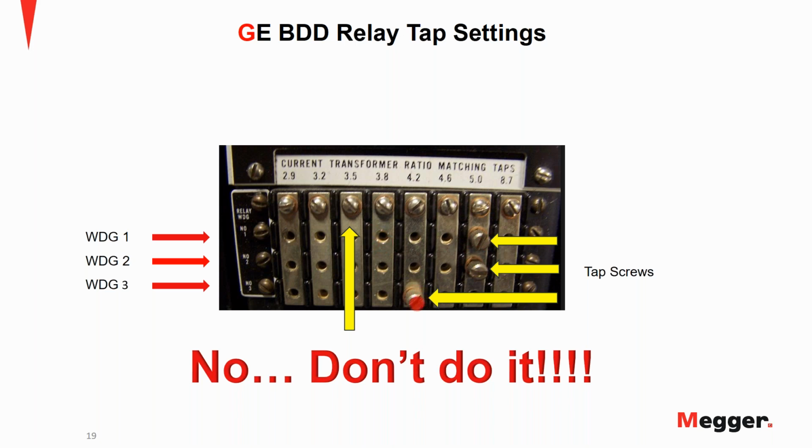If you decide that one day you want to tighten these up a little bit with the inspection you do on your electromechanical relays, and you twist this guy just a little too much, then he's going to end up breaking this head off. That's a bad day, I'm not going to lie to you. This is when you pull this tap out and you put it in this relay and you twist the head off of it, then you need some tools because you're going to be in panic mode at that point trying to get that screw out.